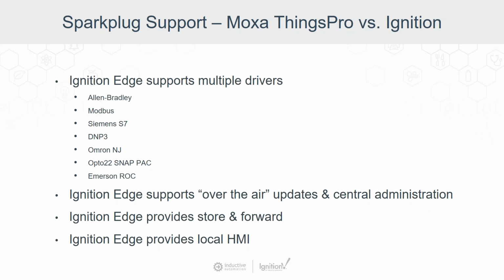But then there are these different polling protocols, and sometimes the equipment will be able to communicate to that PLC directly, poll it, and publish through MQTT. And ThingsPro does that for Modbus in particular. With Ignition being on that equipment, then we get access to a lot more of the drivers. There's more drivers that Ignition supports there.